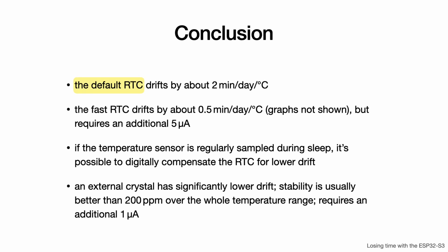So, use the default RTC if its drift is acceptable for the application. And if you require lower drift, use an external crystal.